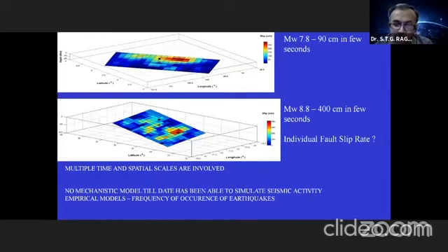Things become very, very complicated, and there is no mechanics actually. Generally, whenever we do structural analysis, the first thing to do is to write the equation of motion. But in earthquakes, there is no mechanics model till date which can simulate these types of large scales. So generally in earthquakes, everybody uses empirical models, that is the total probability theorem. Those things only we use in practice.